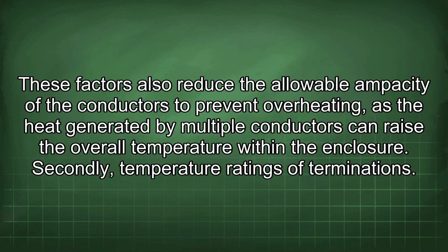These factors also reduce the allowable ampacity of the conductors to prevent overheating, as the heat generated by multiple conductors can raise the overall temperature within the enclosure. Secondly, temperature ratings of terminations.